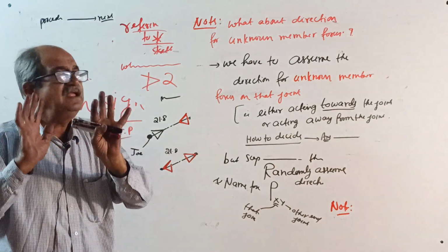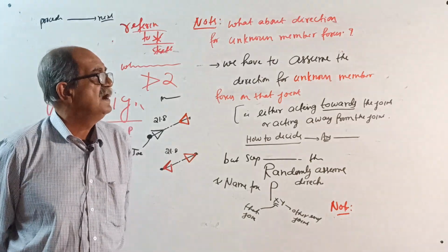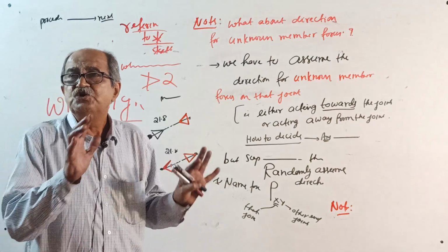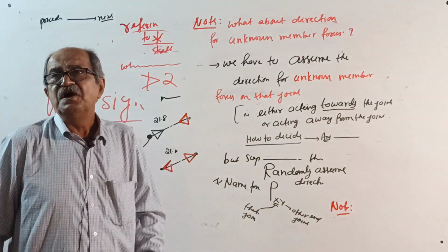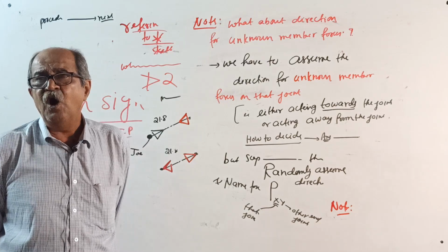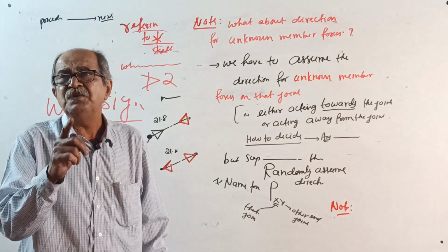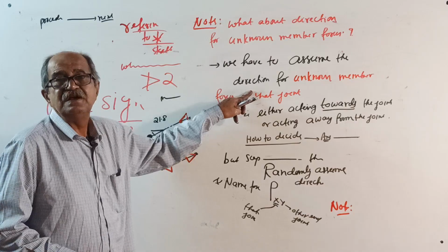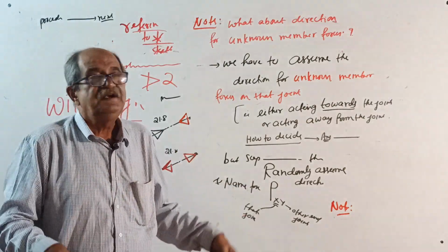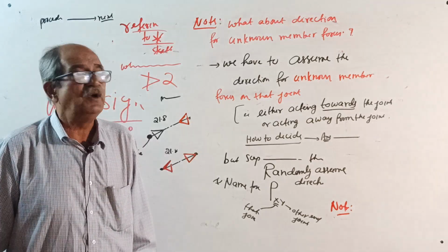Okay, now I will stop the writing. Continue the procedure. Again apply sigma V = 0, sigma H = 0 and get the unknown forces. Immediately enter in the star sketch. Cumulative entry. That way complete the procedure till forces in all members are calculated. And make a note, each time you enter in the star sketch the result from a joint and immediately the other end arrow mark, take a photograph and preserve it so that stage by stage you will be knowing.